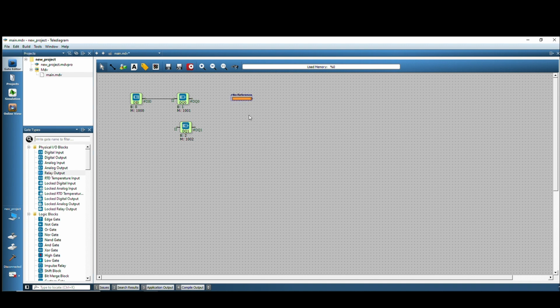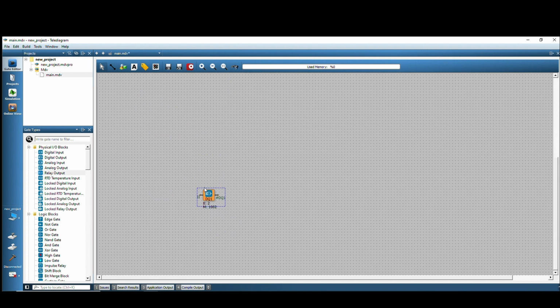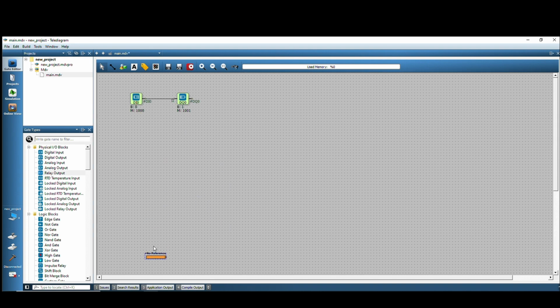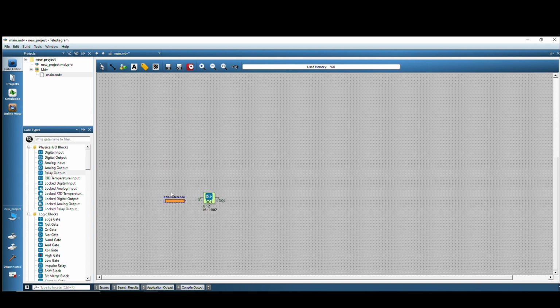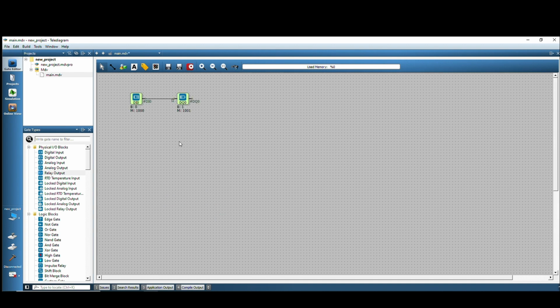The next icon is for adding line labels. Let me give you an example related to this. You have a very large-scale project. You are using many function block diagrams and say you wanted to contact multiple outputs with one input or contact a different function block with the same input information. Normally, we can make such connections multiple times, but as I said, in projects where many blocks are used, this can cause a visual clutter. Instead, we can address with line labels.